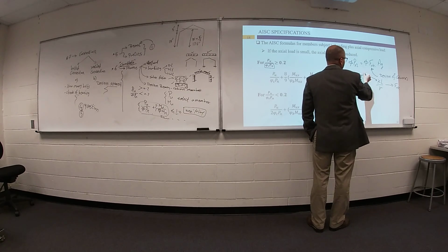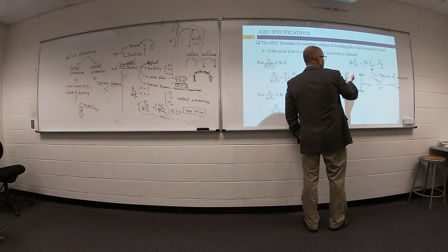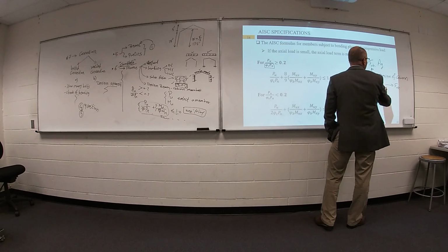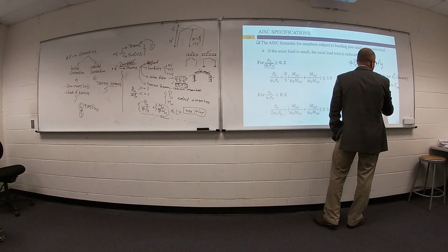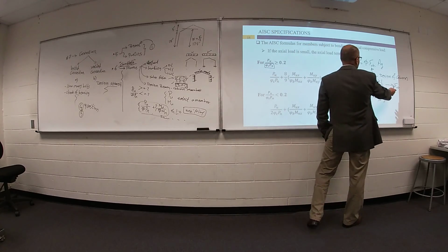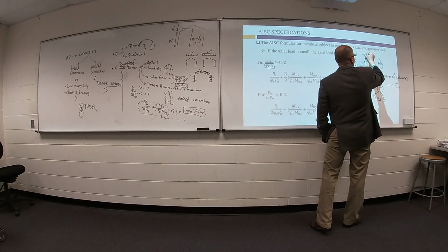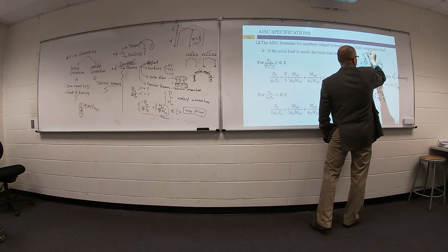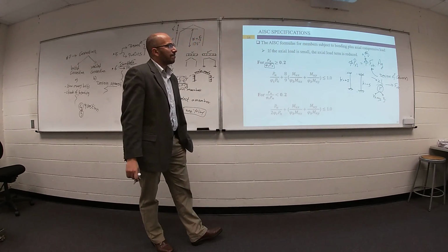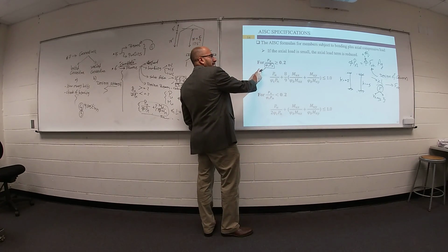K depends on the condition of your column. If your column is fixed, K equals 0.5. If your column is hinged, fixed, your K will be 0.7. What is the L of your column? What is the R? We have two R, Rx and Ry. I will use the smallest value. Based on this, I can get F critical, area gross from the table, and phi. What's the value of phi? 0.65 or 0.75. Anyway, go ahead and get your value and get your design compressive strength.